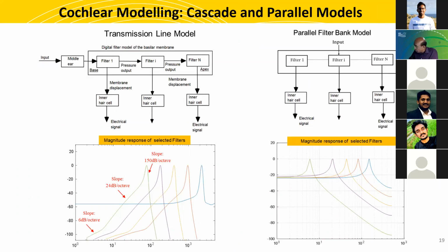Oh, next slide, sorry. I'll come back to that next one. So most of your front end, most of your speech application or machine learning application, your filter banks are not cascaded filters. They are all parallel filters like this. Filters are in parallel, one, the next one, next one. They're not connected to each other. It's easy and simple and very easy to implement, so almost all the people will tend to use that one. They don't use the cascaded one because it's too hard.